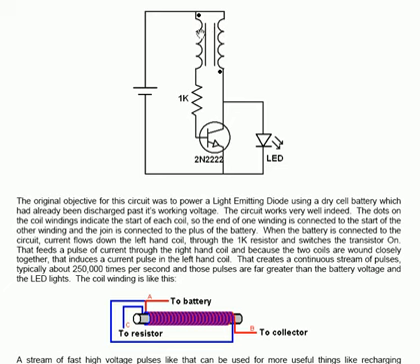The battery voltage can be as low as, say, 0.2 volts, but you could get typically, say, 11 volts coming off the collector. That 11 volts is pulled down by the LED, typically to its operating voltage, which is generally about 3 volts. Depends on the particular LED.